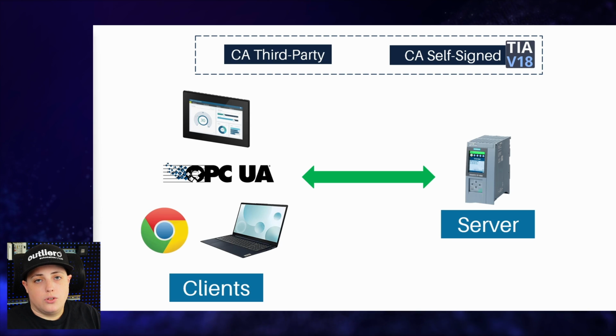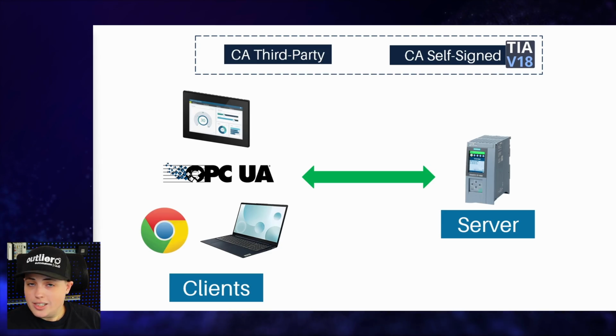And in that case, you could use a certificate authority that is self-signed. That means that basically you are setting up and saying like, hey, I know all these parties involved. I'm just going to say each side, you should trust each other, and I'm making a certificate for you. As long as the dates are legit, then that's okay. So in Siemens and TIA Portal, you can actually use the project itself as a certificate authority. And the first time that you load it, it will create that trust, and then going on, it will make it be encrypted communication.